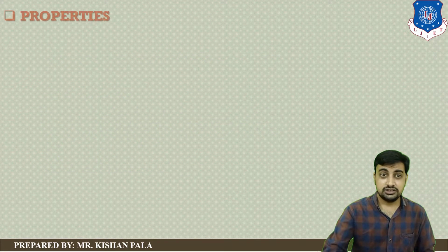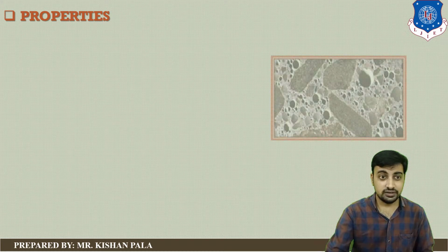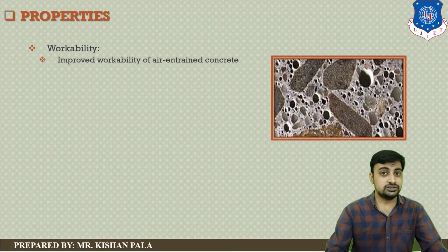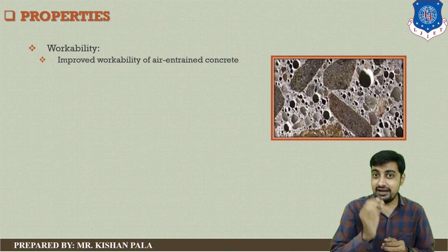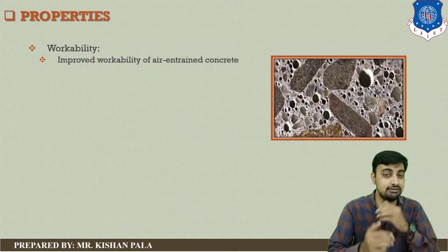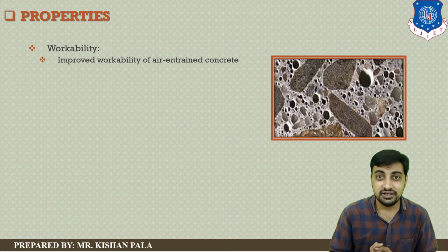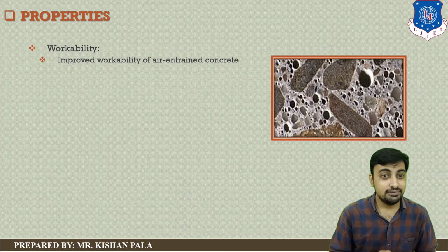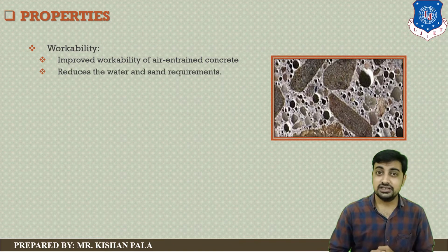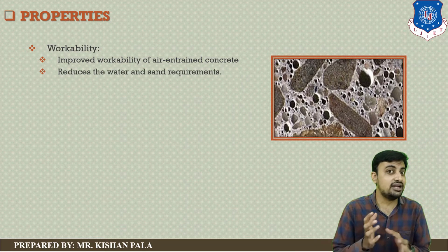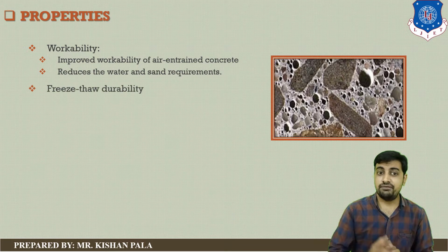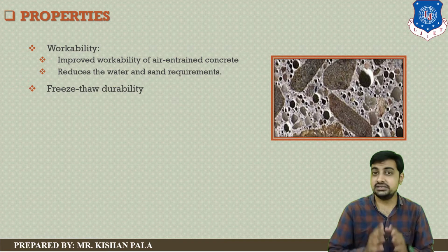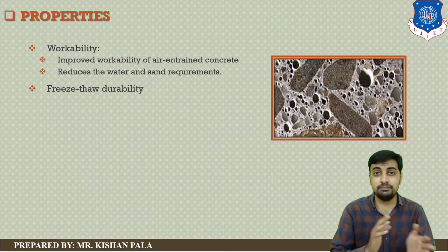Now let us discuss the properties of air entrained concrete. Air entrained concrete has high workability because you are adding the air entrainer to the concrete mass. In that case, the workability of the concrete mass increases, and this is beneficial to the fresh property of the concrete mass. Second, this reduces the water and sand requirements. Next is freeze-thaw durability. As we know, the freeze-thaw effect occurs due to changes in temperature.